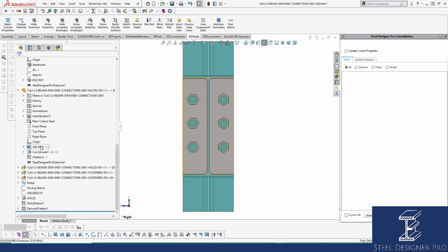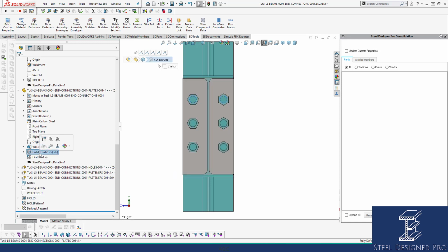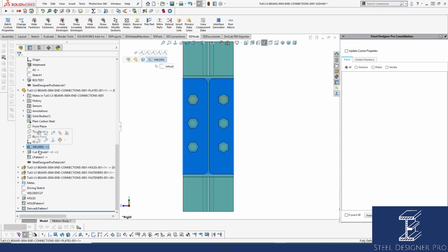You'll notice that inside the plate we've called it welded, so we know that that plate is going to be attached to the welded member. It's not necessary to do that, but we did that anyway. That doesn't always apply to all of our connections, and that name doesn't really mean anything apart from the fact that we know that it's being welded. Most of our plates that go into connections have to go to the welded plate because that's the member that is going to be inserted upon.